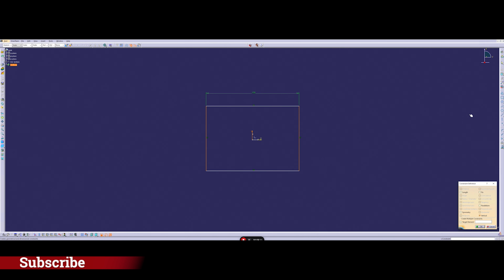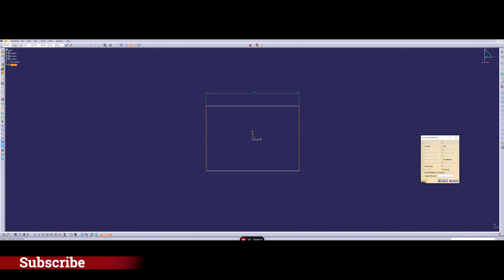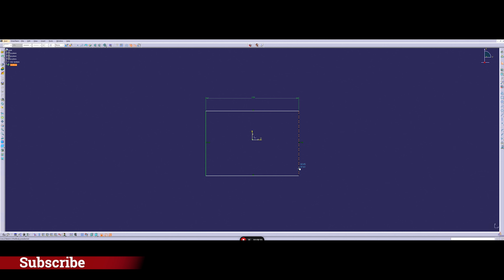When we do that, we see that we have activated another icon up here. If I click this icon, then I see that I have the symmetry option available. When I click it, and after click OK, you see that here I have two new symbols that say that my design is always constrained to the vertical axis.